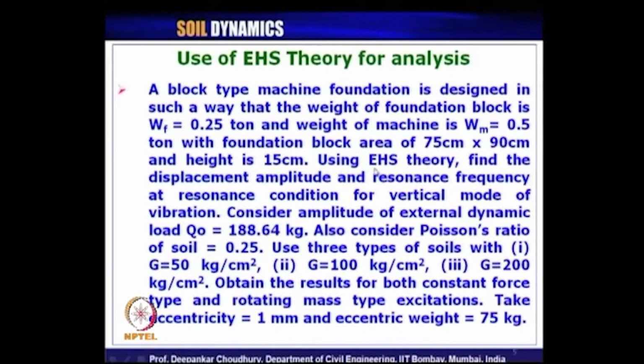Now, using elastic half space theory, find out the displacement amplitude and resonance frequency at resonance condition. So, this is the new thing which we are going to compute. Earlier we computed for operating frequency condition what are the displacement amplitudes. Now, we are computing it for resonance condition. For which mode of vibration? For vertical mode of vibration we need to compute.